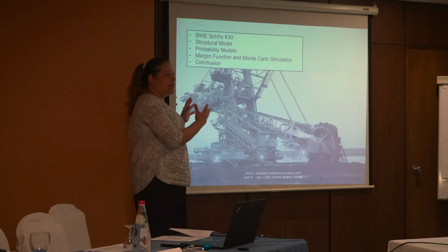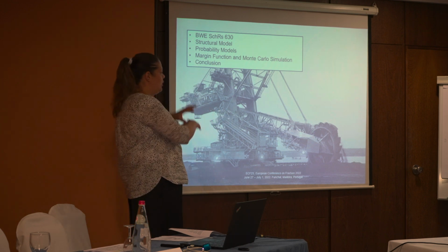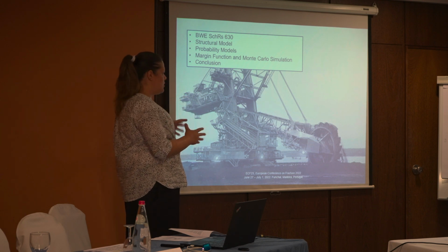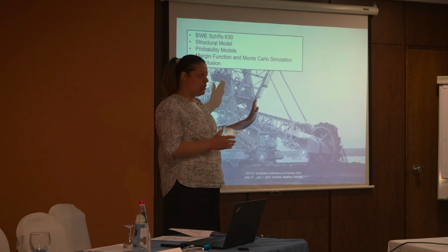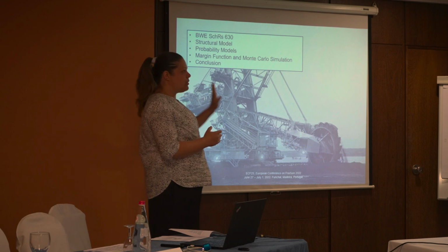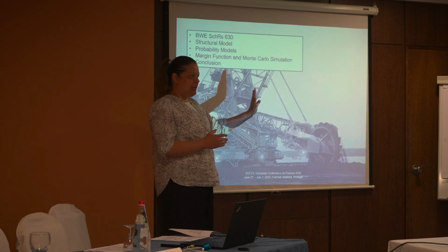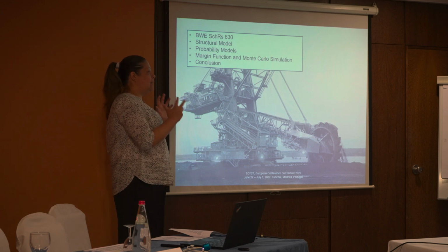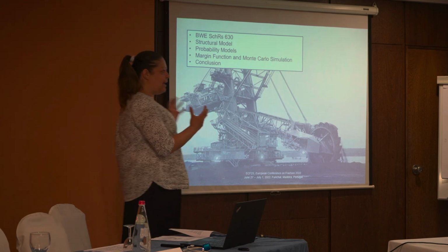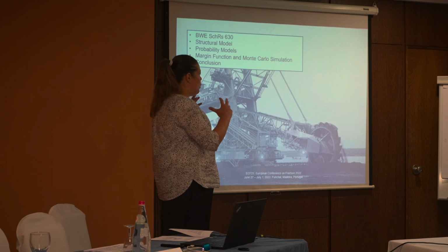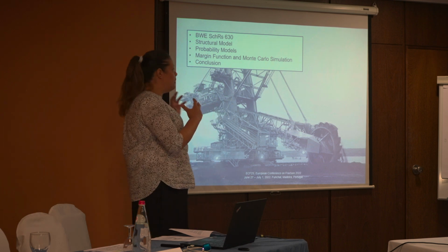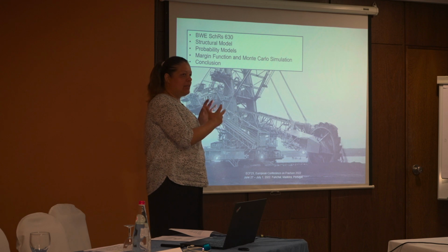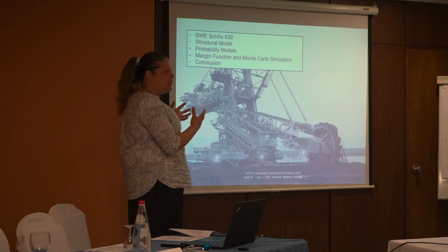When you assess a construction, you usually do some numerical calculations, you get stress concentrations, and you compare stress concentrations to the yield limit. And in that way, you don't get into your analysis the overall structural response and all the uncertainties that could happen to that construction.